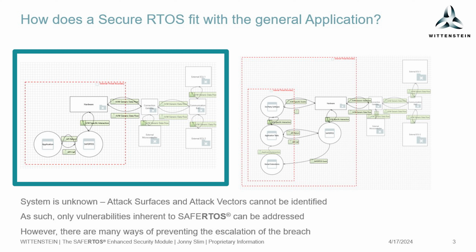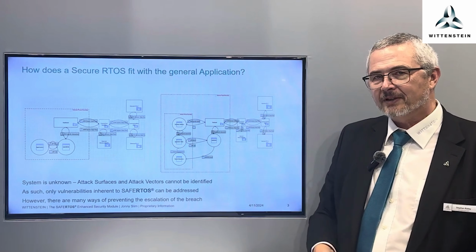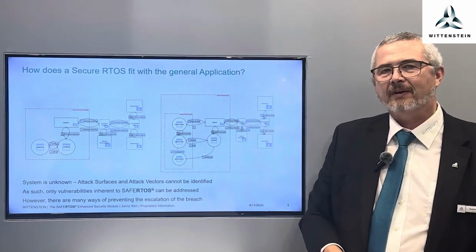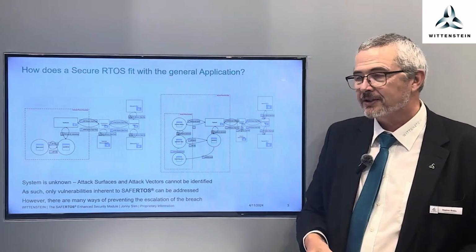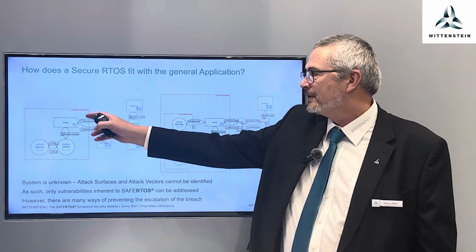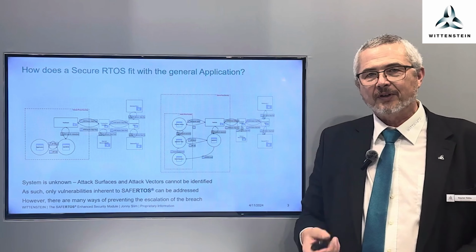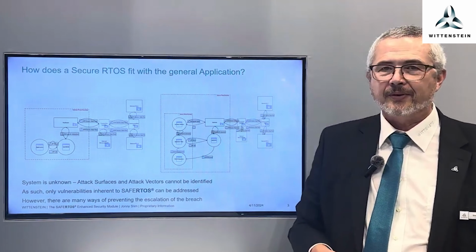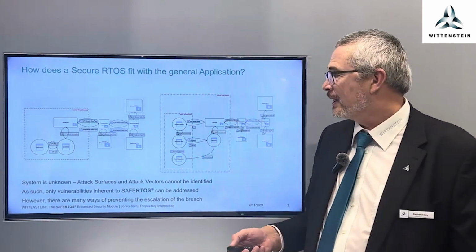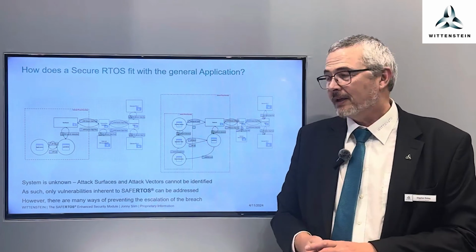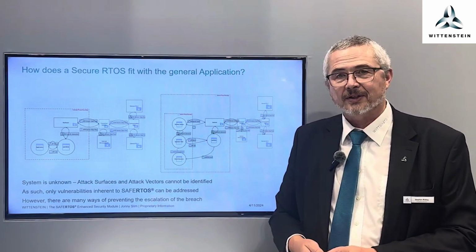In this scenario, it's quite defensible to draw the threat boundary around the whole ECU, which means that from an RTOS perspective, you don't need to worry about extra security. It's enough to implement protections or protocols on the communication bus and the usual things you would do with root of trust and protecting physical access to the ECU.